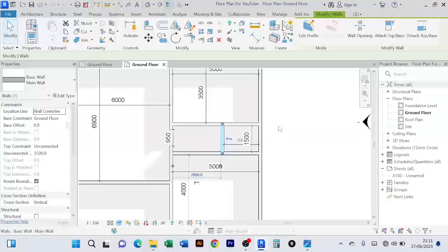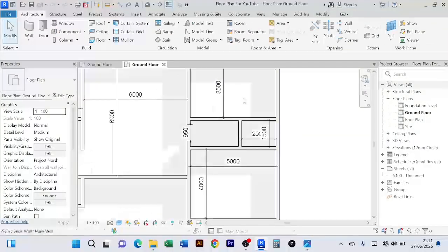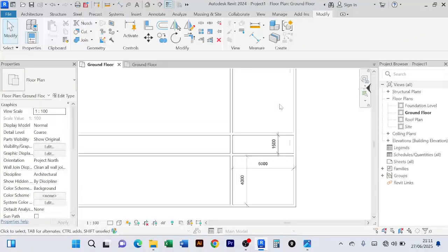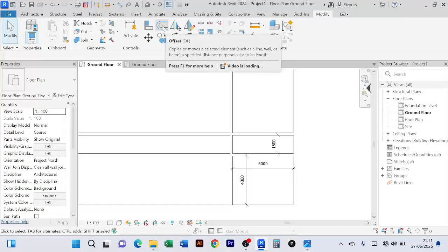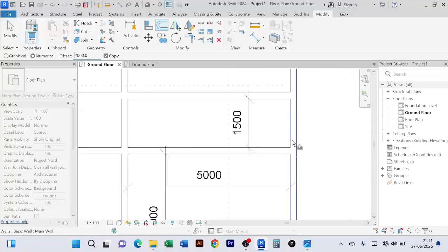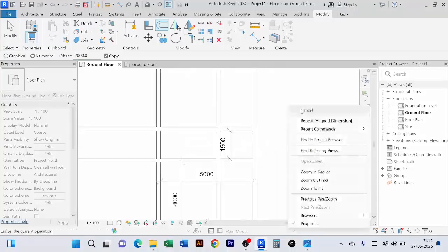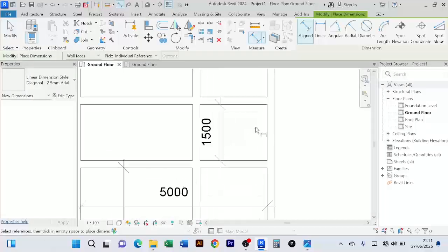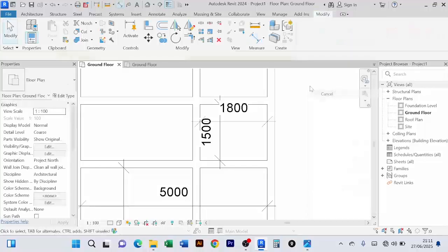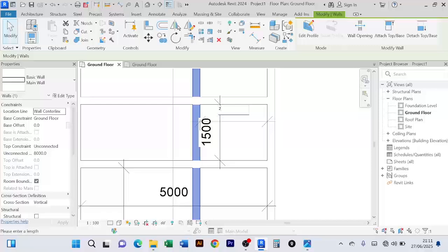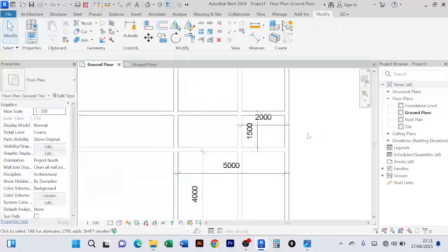It is just 2 meters from this wall here. So we shall just offset this wall 2 meters inside. We go to the offset tool, the OF, then you offset 2 meters from here. But of course, we are supposed to escape. Then we can go to the align dimension tool. You measure this and measure that, and you have to ensure this is the distance that you have specified. When you click on this, we can change it to 2 meters, because that is what we want to achieve.